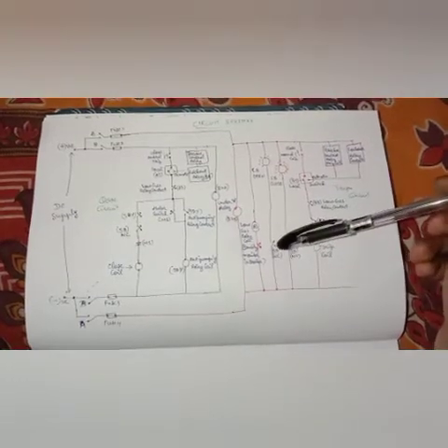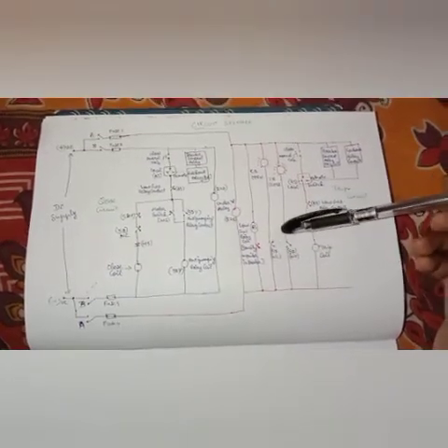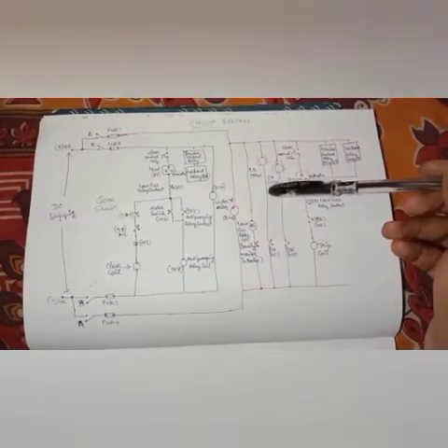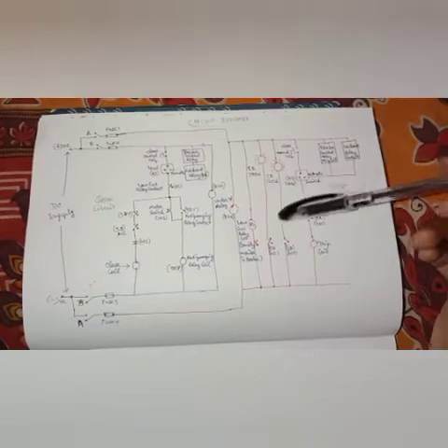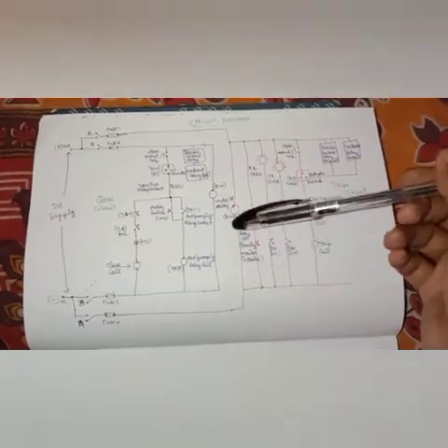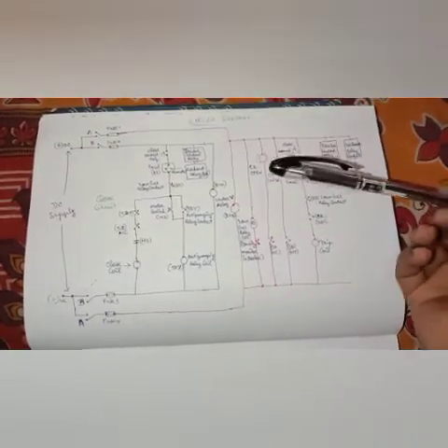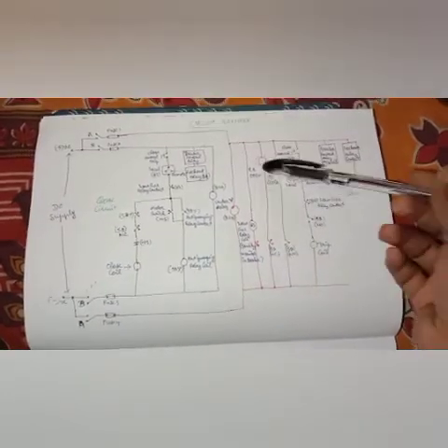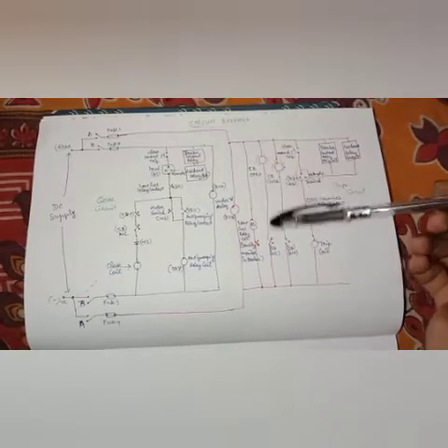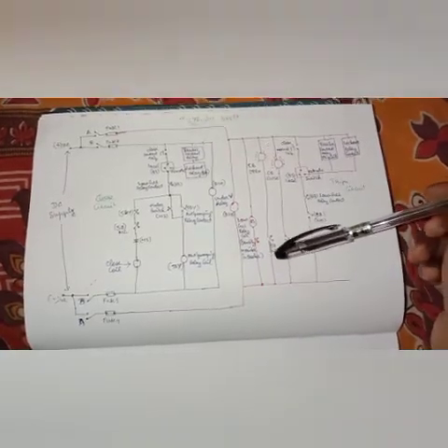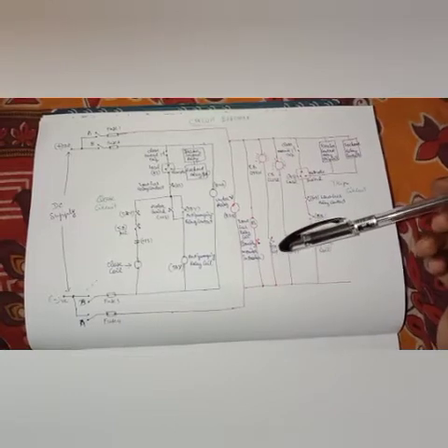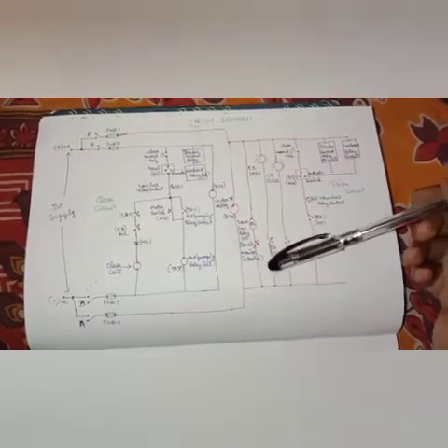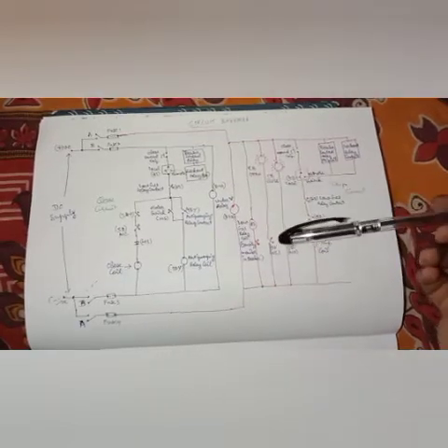Next, coming up to the breaker status, which means open and close status. Like in a breaker marshalling box itself, you can see the lights glowing as open and close. For open you will use a green light, and for close you will use a red light. How the indications are shown, it's a simple thing. The auxiliary contacts which we are using for the breakers, with that itself you can indicate the breaker status.